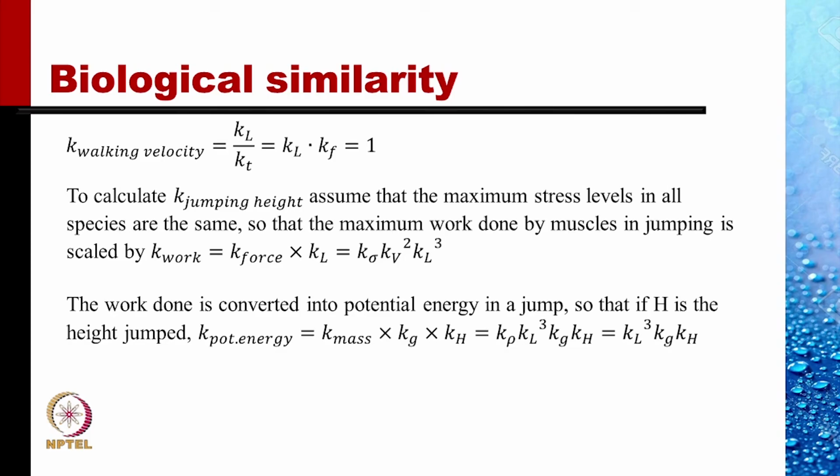K work is K force into KL, and K force is like K sigma into KL square, so that K work is like K sigma into KL cubed. K sigma is 1, the stress level being the same, so the work done scale factor is like KL cubed.